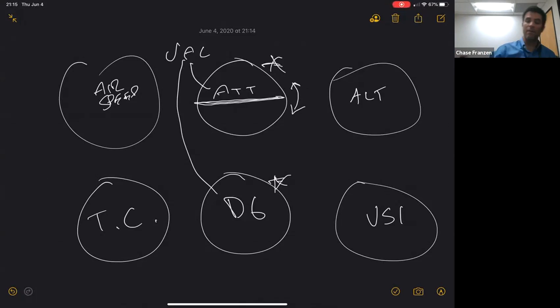As your airplane moves, your airplane is actually moving around that spinning gyro in space, and that spinning gyro is resistant to wanting to move left and right with the airplane. That gyro is connected to the mini airplane that you see on the attitude indicator. So all that's happening as you bank left and right is the instrument is moving around the spinning platter, or the spinning disc, connected to the miniature airplane. And so you see the artificial horizon moving around that airplane.